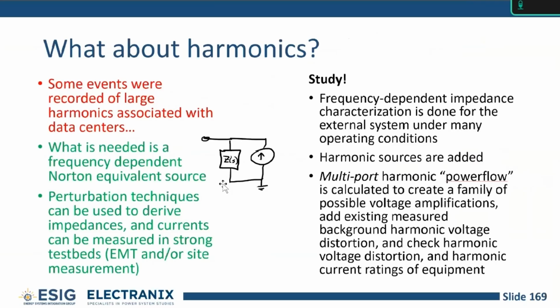Okay, so just another caution with shunt capacitors: the more you add, the more likely you are to start occasionally hitting bad harmonic amplifications at problematic harmonic frequencies.